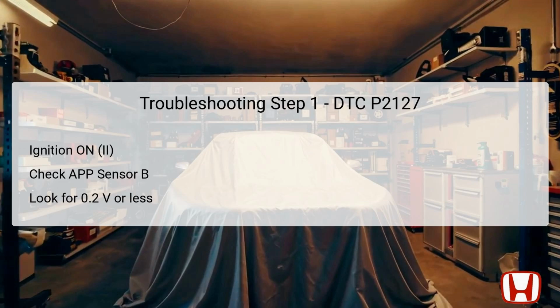In the first step of troubleshooting DTC P2127, ensure the ignition switch is turned to the ON position. Using a Honda Diagnostic System HDS, check the readings for APP sensor B in the data list. If the voltage measures approximately 0.2 volts or lower, this confirms the failure, prompting you to proceed to step 2.